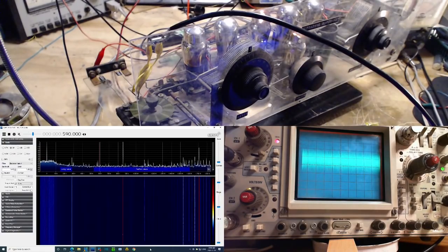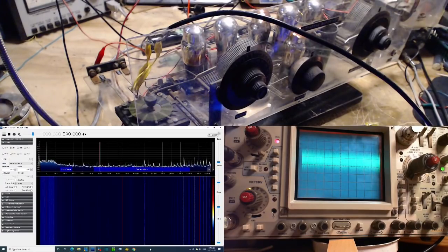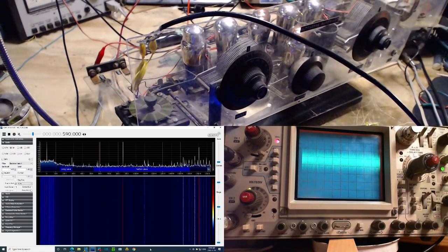And now I'm going to stick a signal into that coil up where we think we're tuned. Should be maybe, I don't know, 600-700. I don't see it on that, so I should see this signal on the SDR. I don't see it anywhere. Am I doing something wrong? Signals are all up. Definitely a 680.